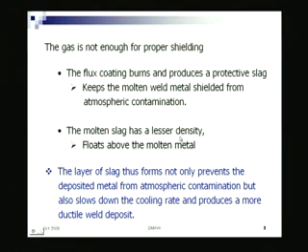This molten slag has lesser density, thereby it floats off the molten metal, because when I am welding, your metal is getting melted, flux is getting burnt, forming slag, and that is also in a molten state. So, both are mixed, but the molten slag being lighter, it will float up the molten metal.